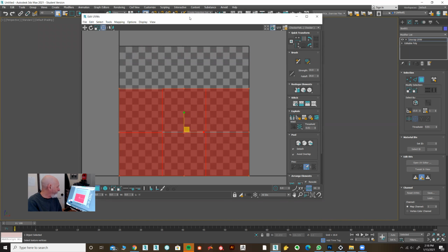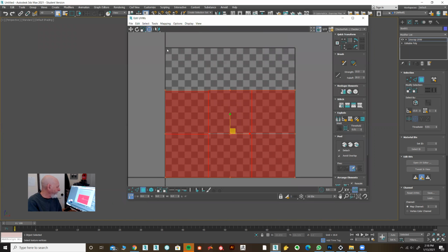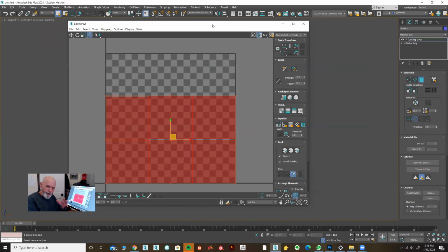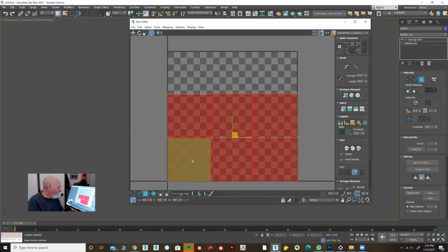And it gives me this, all right? So this area, what it did is it unwrapped. What you're doing when you're unwrapping UV coordinates is you're taking a volumetric 3D object and trying to flatten all its surfaces so you have a file that you can paint on, and that could later be wrapped back on the three-dimensional object. And so this is a cube, right? So it has 6 sides.